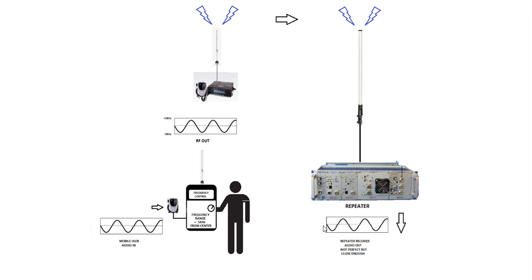So we're going to start right here with the original audio coming in, and this would be the voice of the mobile user, and this would be vibrating air vibrations coming in that's hitting this microphone right here. Now, this microphone has a little crystal inside it called a piezoelectric crystal, and it has a unique ability of taking mechanical vibrations and translating them into equivalent electrical signals.